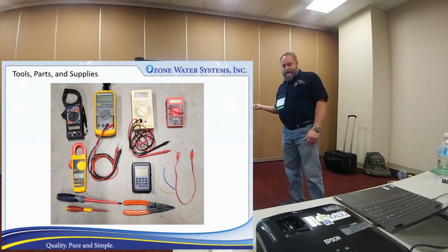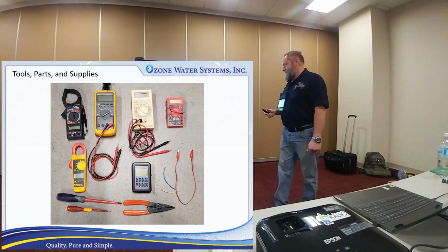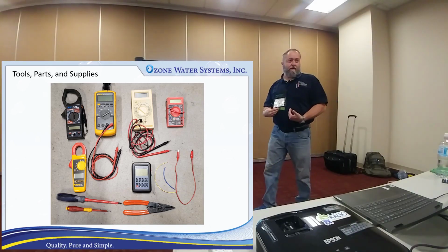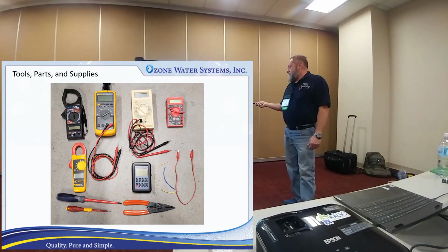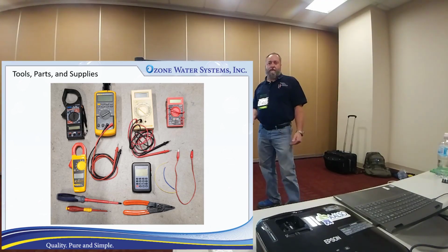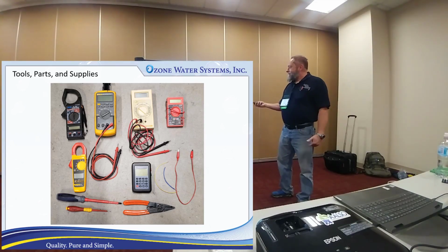It's a process calibrator. It'll actually produce a 4 to 20 milliamp signal, or read a 4 to 20 milliamp signal, but even the cheap meters like this one will read a milliamp signal. This one will produce it and read it. I got this one off of eBay, but if you need to simulate a 4 to 20 signal to something, they're pretty handy if you know how to work it. But you don't have to have that.